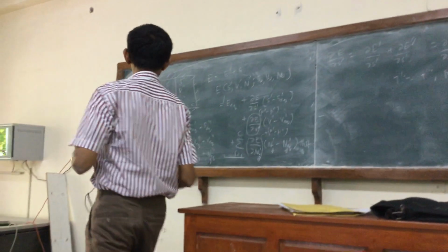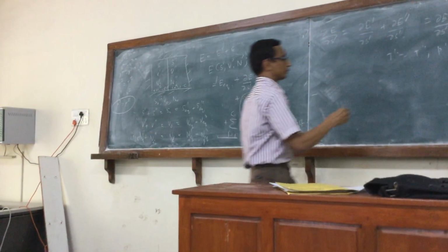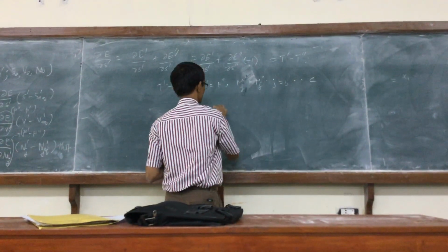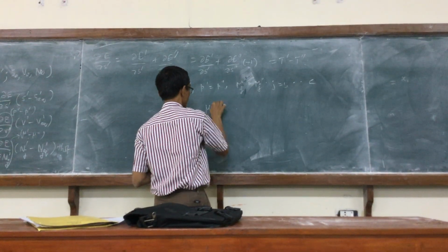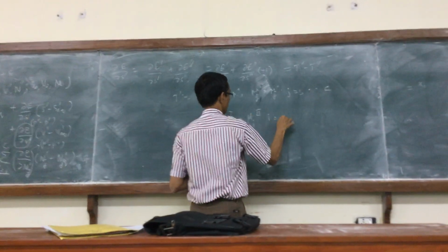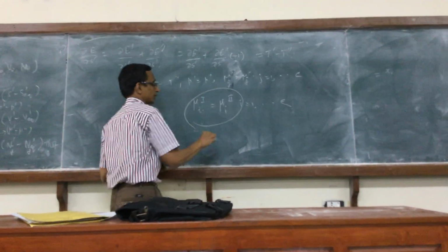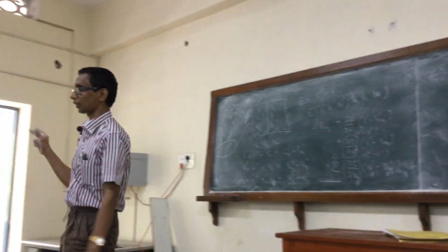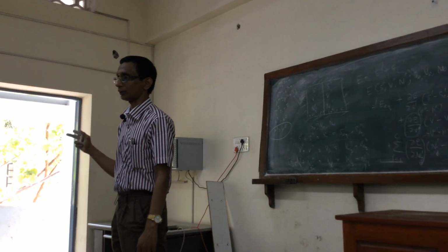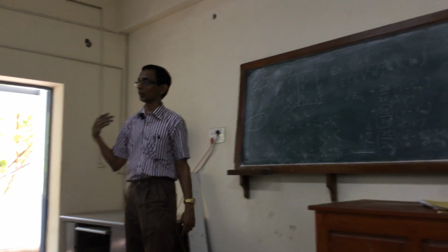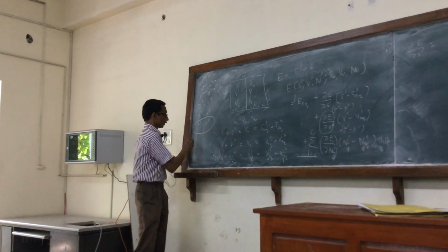But now if I want to apply this between two phases, this would take the form mu I1 equal to mu I2. So we need to be able to relate the chemical potential of each phase to some equation of state or some other quantity, just as we did for the pure compound. We took the criterion mu L equal to mu V.